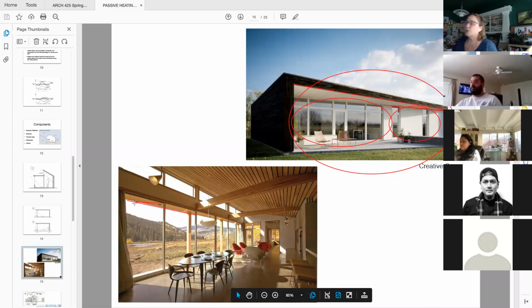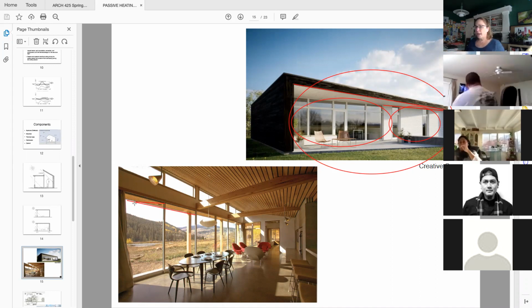And what you want to do is look at your climate data and determine, okay, so I'm building something in Montana, but it doesn't get warm in Montana until May. Okay, so we want deeper overhangs. No, excuse me, we want shallower overhangs because we want more of the year of that sun to come in, versus here in San Diego, it can start getting warm in March or April.